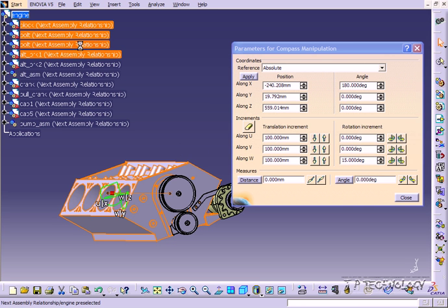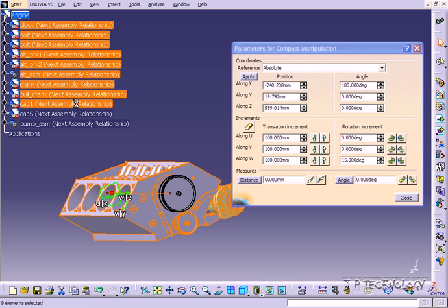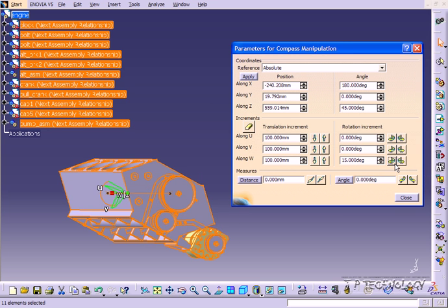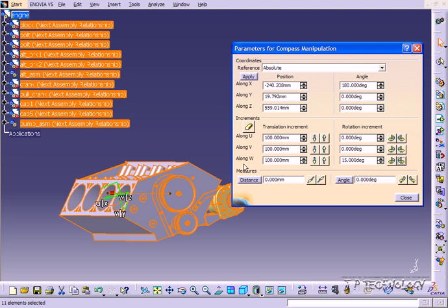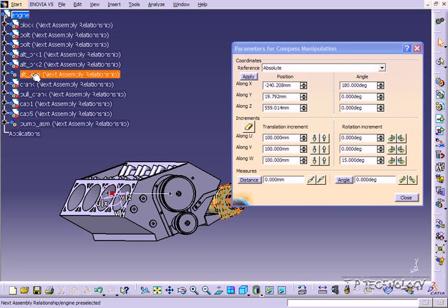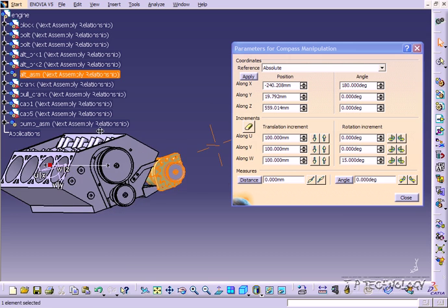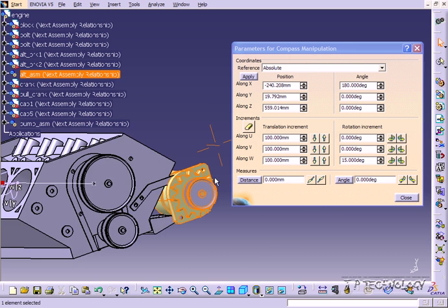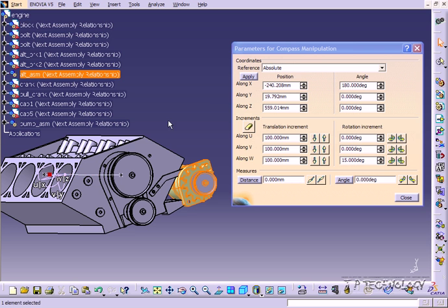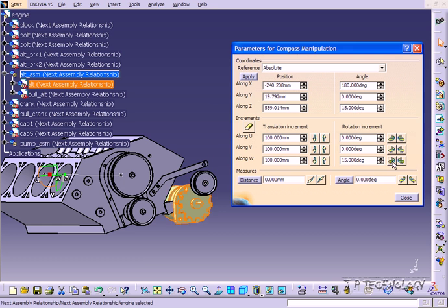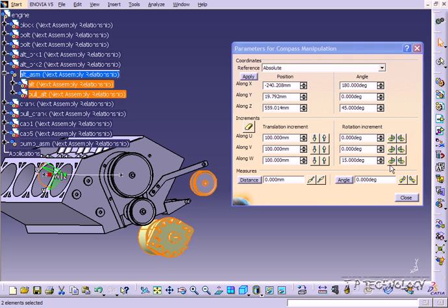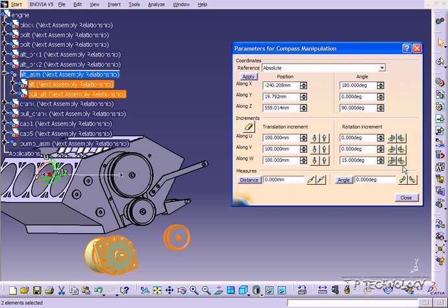Now let's do the entire assembly. So highlight everything. And once you have everything highlighted, start rotating everything around. And everything's going to rotate. And again, we can do this to a smaller assembly. So double click the alternator here. We're still going to use this as our axis point. Open it up and let's just rotate this one guy. And you can see that only he is rotating. And as we select both, we're able to rotate both at the same time.